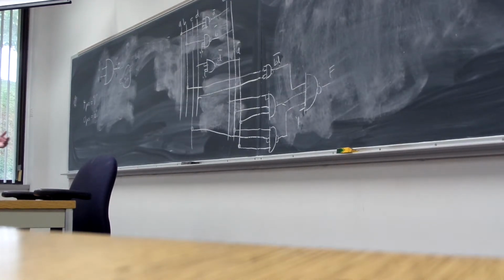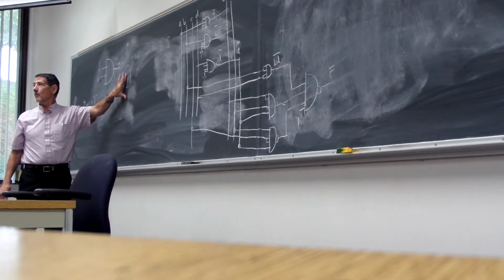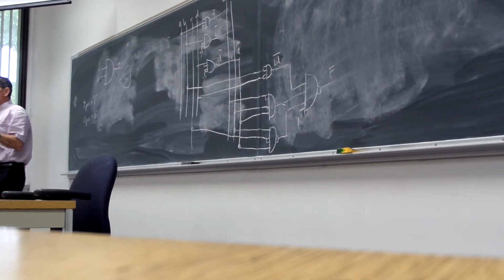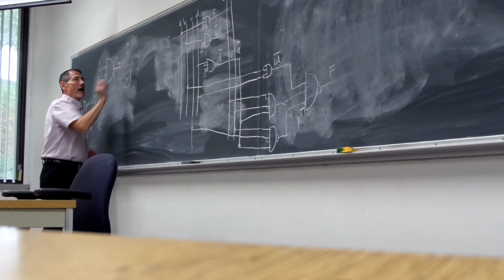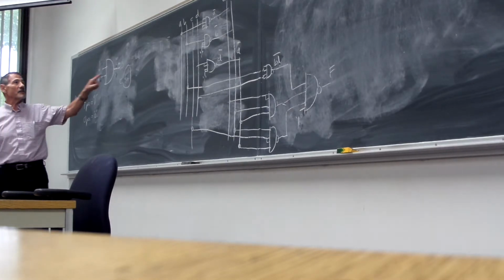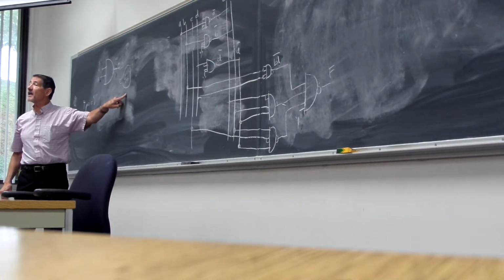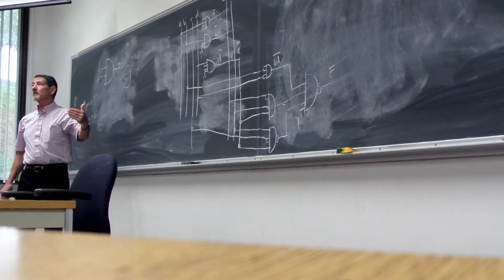So, is this a good load? What would we like our loads to be? Not needless. Not infinite input impedance, if you will, right? No flow. Now, this is a really good analogy because you understand that if I have a sealed balloon there, how much flow is going to come out of this gate to maintain the 4 psi? 0 in steady state. But I had to put some out to get it to blow up.